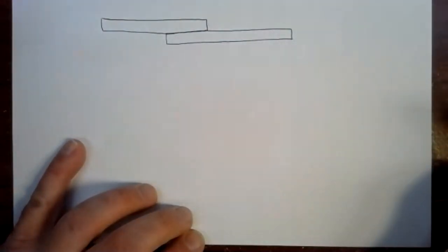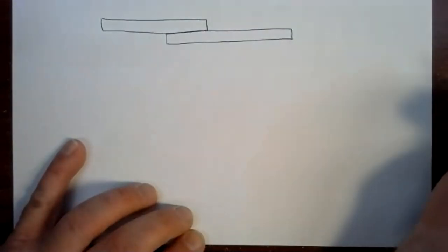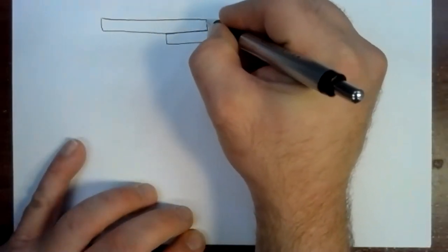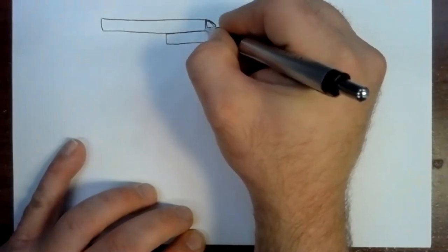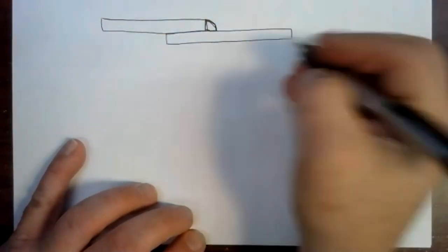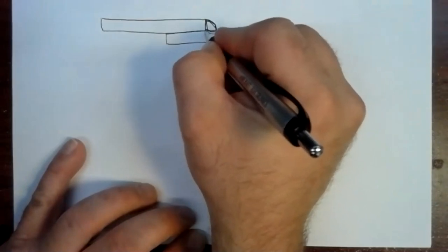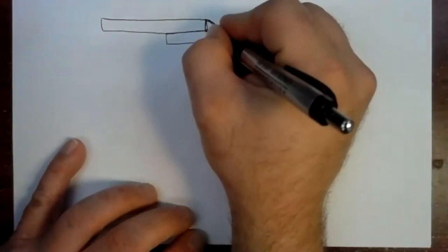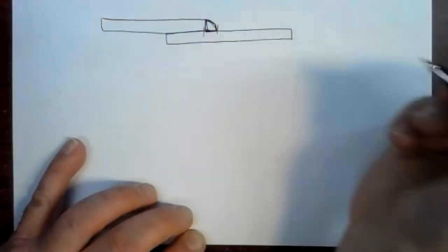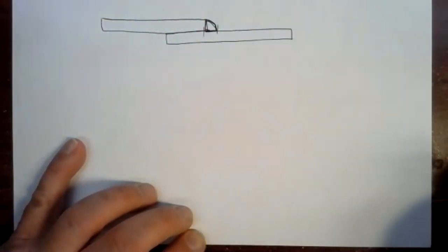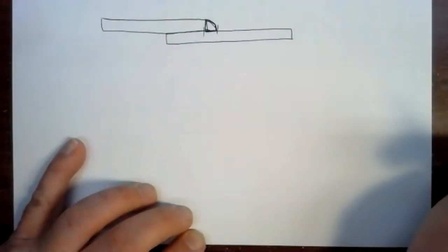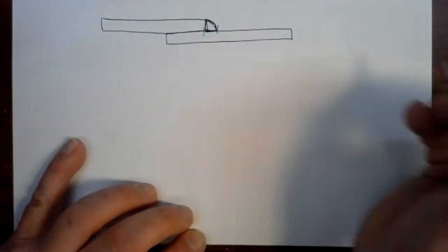If you're doing a flat lap joint, just single sided, we'd weld a bead here, let's say. Well, that bead is in contact with the surface by some amount of area. There's a thickness to this bead and a length to it. There's an area there. So we could figure out what the shear stress on that would be.